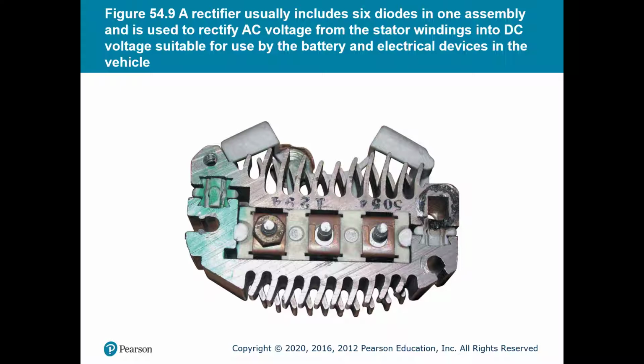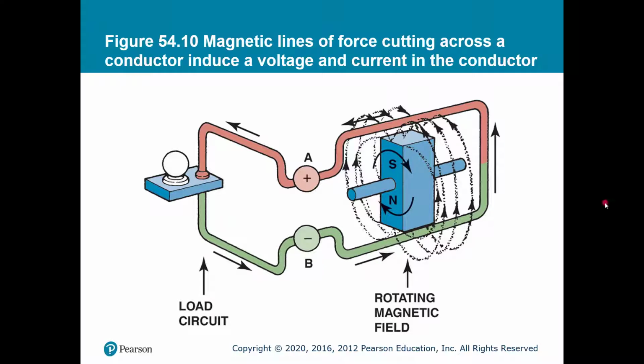So to better explain how phases work, in this example, as this rotor were to spin, this magnet right here that I'm circling with my mouse, as that were to spin within the phase, the A and the B, as you can see here, the A being the positive side and the B being the negative side, is essentially one coil, and that would be referred to as one phase. If we only had one phase, things wouldn't work very well. I'm going to show you an animation I made years ago that helps to explain this.